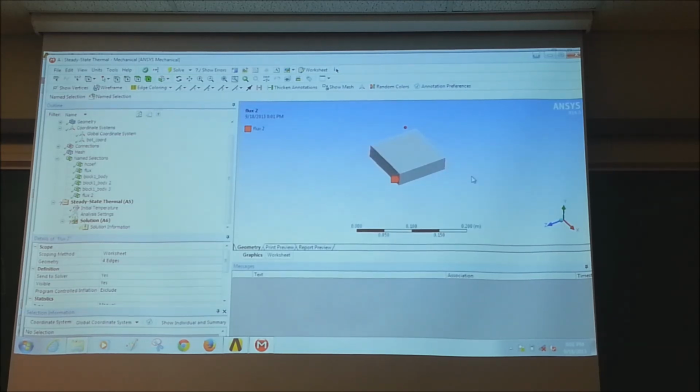So I want to at least finish this thing, so I won't use that. What's your motivation for removing edges? Because what you're trying to do is this. Let us say you want to use the sweep method, right? And you really want to control the number of elements in the Y direction, X direction, and the Z direction. You can do this, and now I have this group. I'm going to rename this. Good question. I'm going to call it bottom